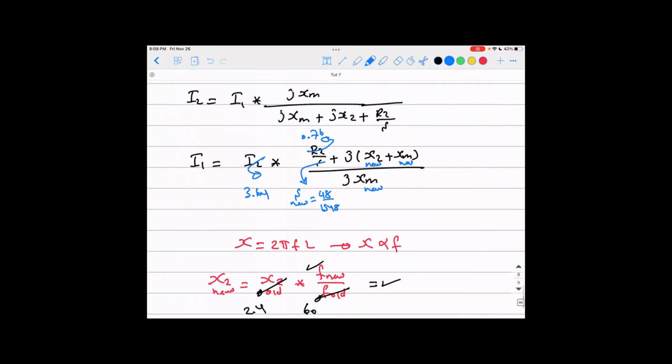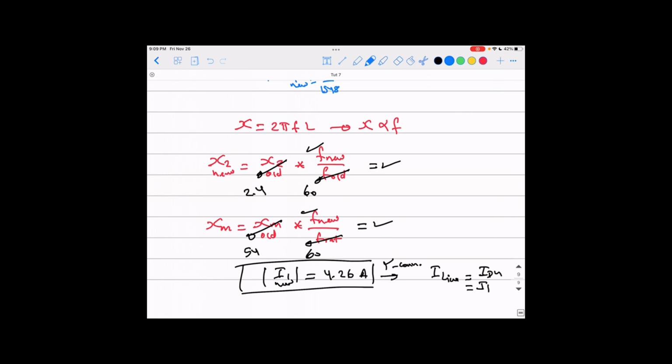Okay. That's it. So I hope this solidifies your theoretical concepts about the V over F speed control, and how to go from different zones, from the V over F constant zone to the zone where V stops changing and the frequency can go higher than the rated value, and how you can use this to determine how to set the frequency of the machine and the voltage to find the speed you want at a given load torque. Okay, guys, that's how we do this.